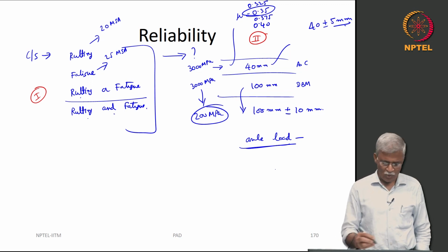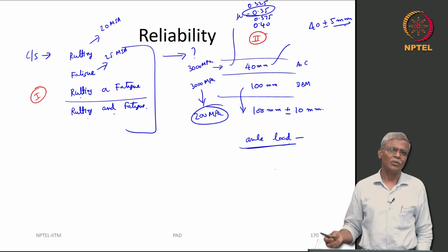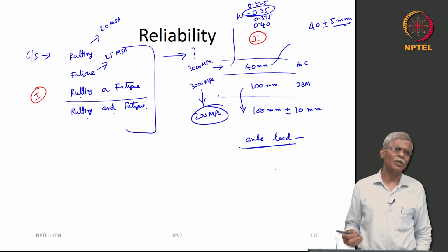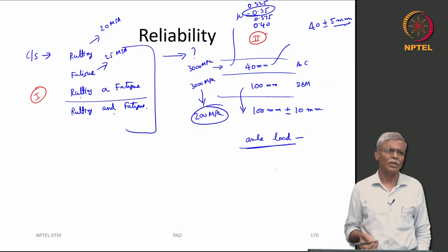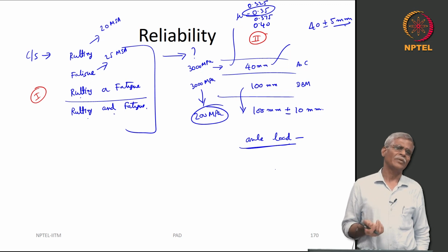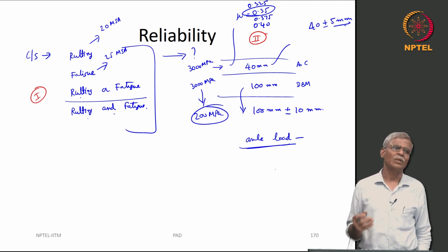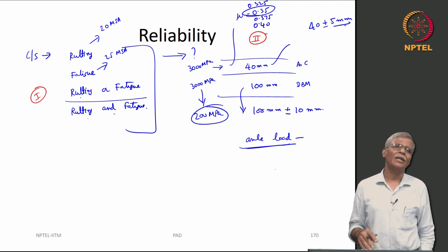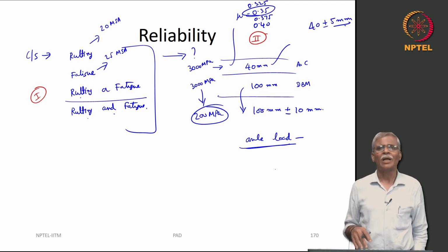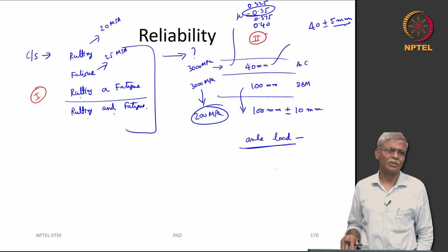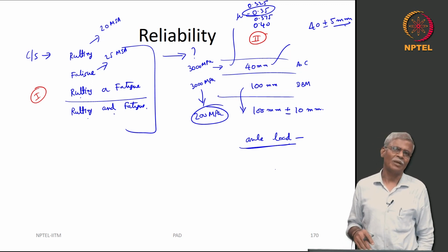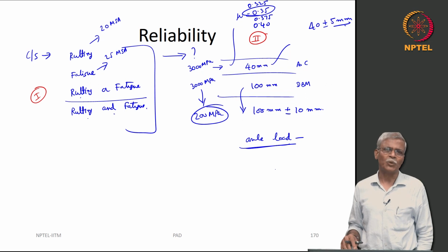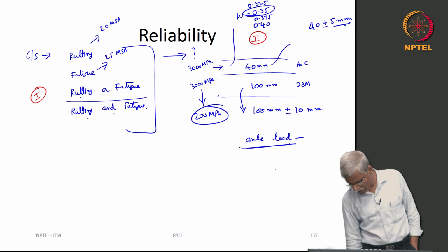I can just keep going on and on, but you have enough ideas here. Now, you can take it and you will also form your own ideas related to doing it. But my sincere request to all of you is, I am sure you have some axial load data that was shared already with you. So, use that, try to compute the vehicle damage factor, try to design a pavement on your own, at least with the IRC 37 method, and see what are all the obstacles that you face. Please do write to us, email us, and we will be very happy to answer all your questions.